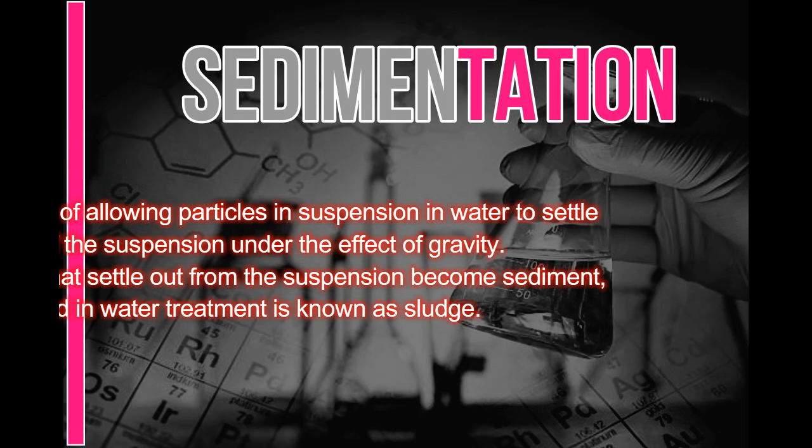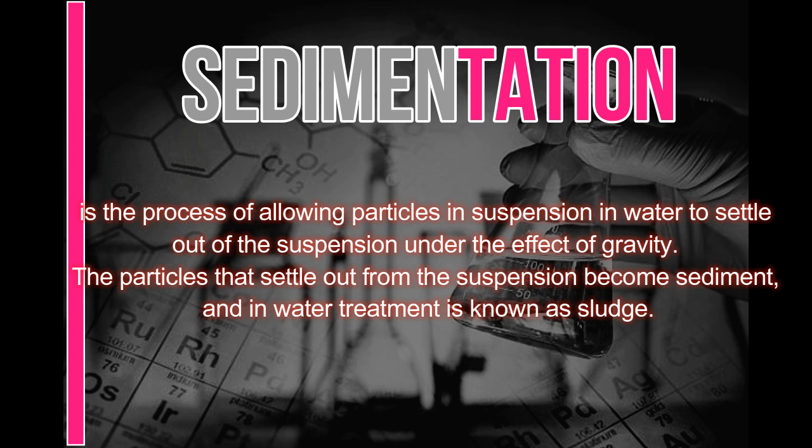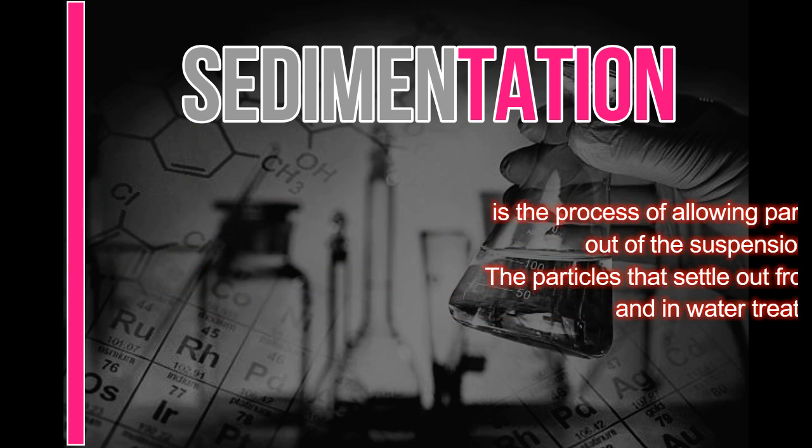Sedimentation. Sedimentation is the tendency for particles in suspension to settle out of the fluid in which they are entrained and come to rest against a barrier. Settling is the falling of suspended particles through the liquid, whereas sedimentation is the termination of the settling process.